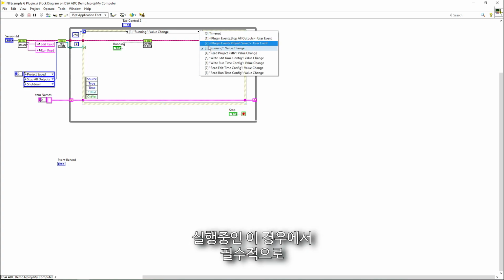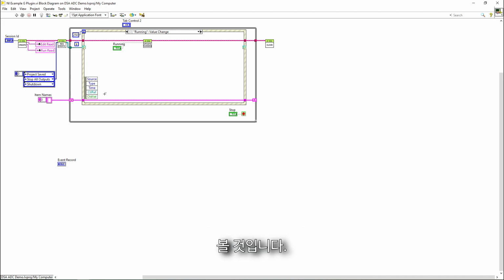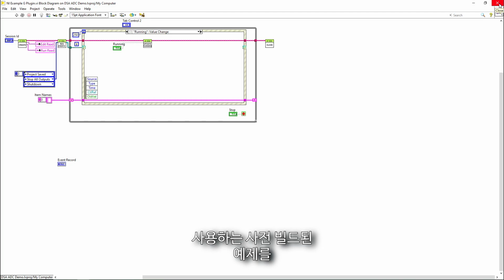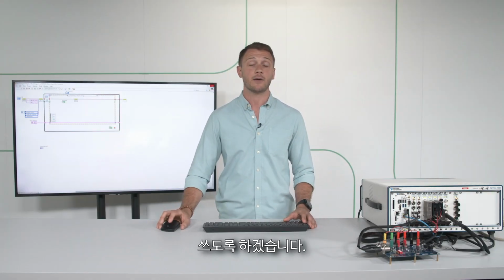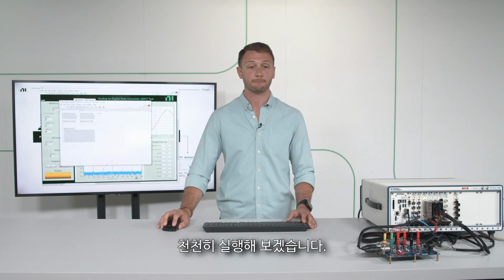But really, you're going to look at this running case right here. And essentially, in this blank space in here, that's where you're going to put your functional code. You can copy it directly in, or you can call out to a sub-VI, but this is where you're going to put your code. Now, rather than trying to do this live in front of you today, I'm going to take the pre-built example where we use that same LabVIEW code from the audio ADC example, and I'm going to plug it in here and show it running in Instrument Studio.